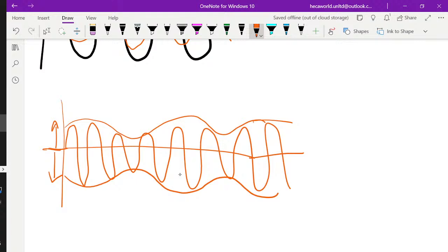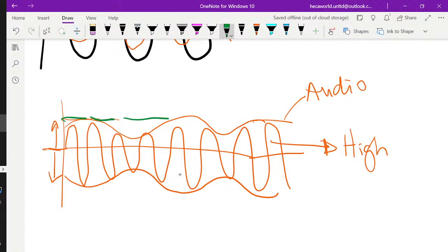This component, the oscillator signal, will be high frequency, and when I say high frequency, I mean compared with your audio signal, which is creating the envelope. So that modulates your amplitude, and your amplitude doesn't stay the same. Let's just use this line. This was your original amplitude, but your audio signal has forced it and created an envelope and compressed and reduced the amplitude of your signal.